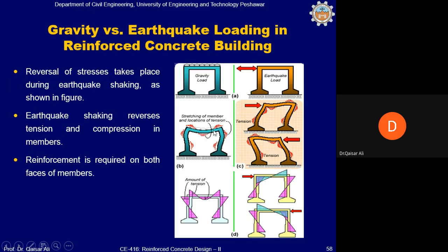This is known to you, and this is very clear to you. The bending moment diagram you would have drawn several times. You can draw the bending moment on the tension side or compression side. This bending moment has been drawn on the tension side. So you can see that the bending moment diagram is like this. Tensile stresses here at the midspan of the beam, and then we have tensile stresses here at the ends of the beam on the upper side of the beam, and so on.